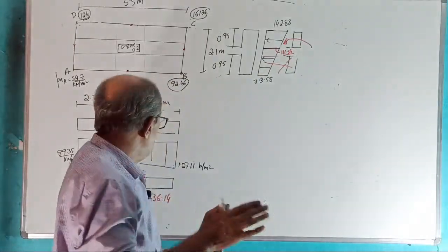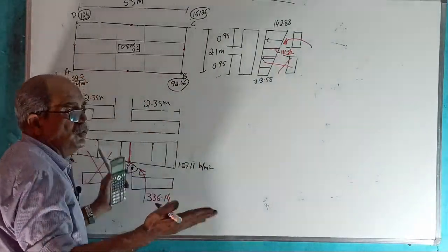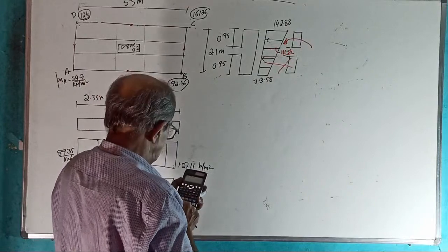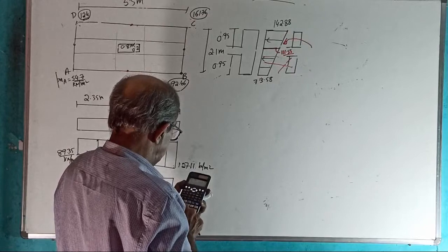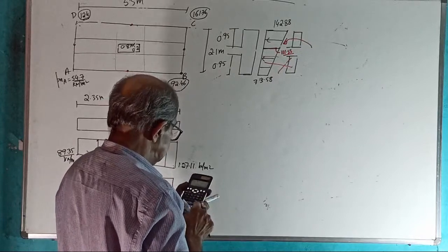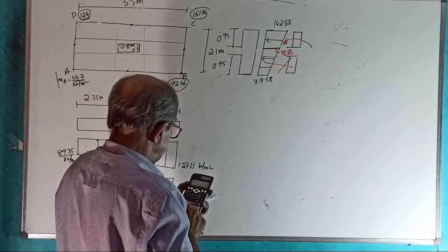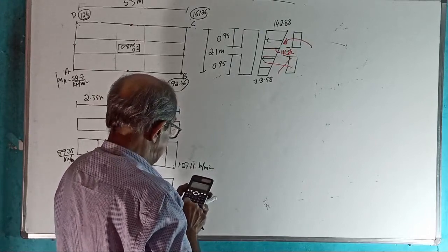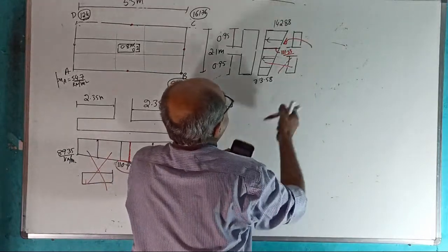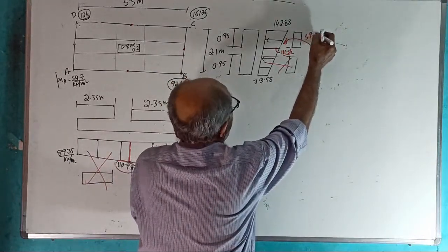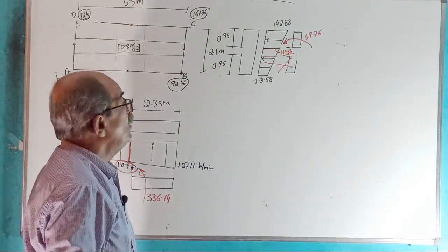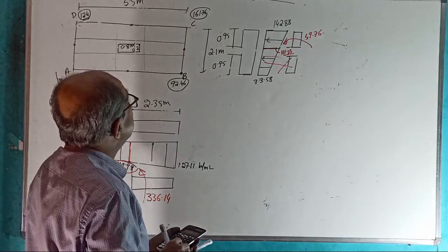Sorry, I told so clearly earlier, resultant load into distance, how much I explained earlier. And there, 111.53 plus twice of 142.88 divided by 111.53 plus 142.88, into 0.95 by 3 is the distance, multiplied by 111.53 plus 142.88 divided by 2 into 0.95. That bending moment is only 59.76. See there, lengthwise bending is so heavy, 336.14. Widthwise bending is only 59.76.